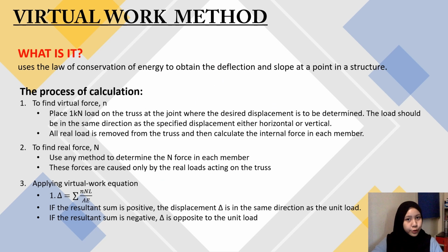Assalamualaikum. My name is Nurul Aisha and I will explain the next calculation, which is the virtual load calculation by using the virtual work method, or we can call it the work energy method. So what actually is the virtual work method? It uses the law of conservation of energy to obtain the deflection and slope at a point in a structure. Why exactly do we apply this method on this truss? It is because the type of truss is a determinate structure with zero indeterminacy. Okay, let us proceed to the process of calculation.